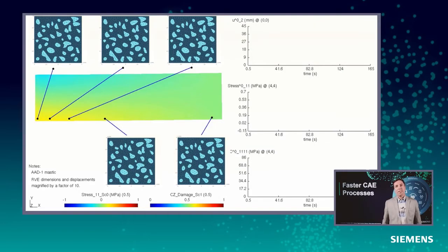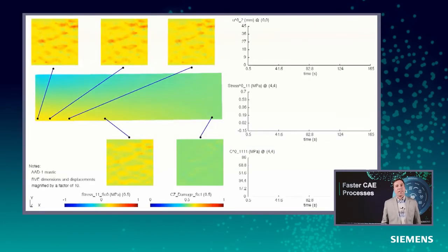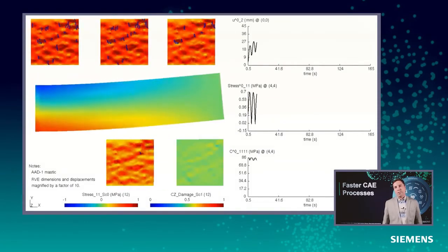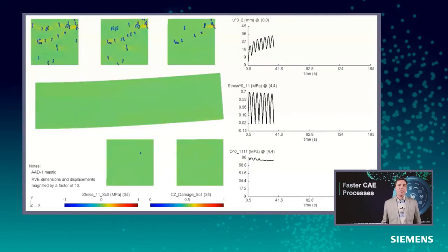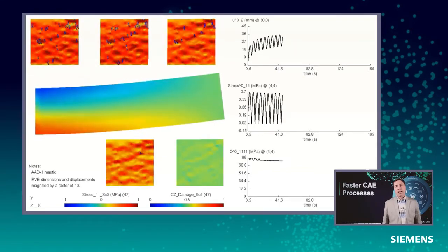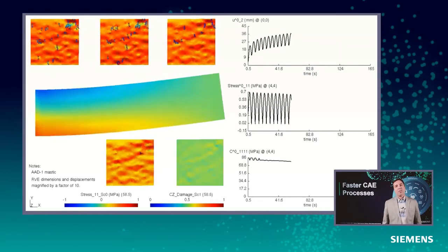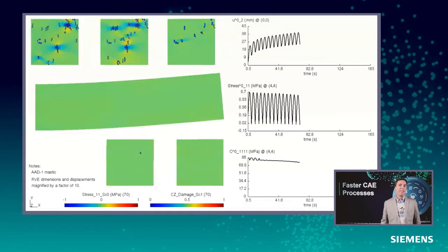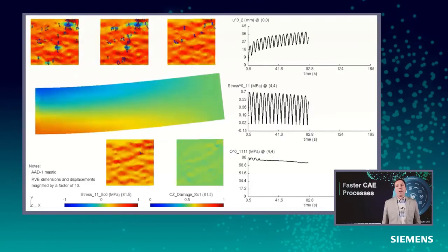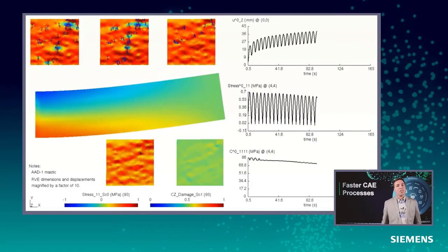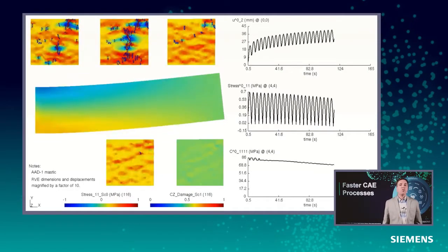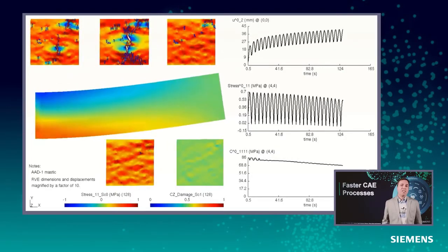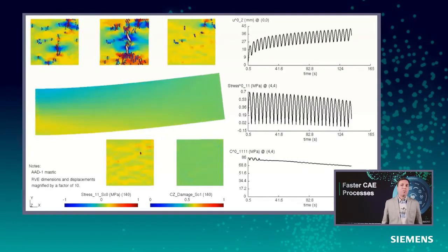In this latest release, we've made crack modeling capabilities faster, as cracking is a very important consideration for advanced materials. Micro and mesocracking in advanced materials are difficult to model with the finite element method, and in Simcenter 3D 2021.1, we've made the task easier by adding full representative volume element separation and automatic insertion of cohesive zones in between different materials. Microstructural models now allow for full mesh separation for a crack to propagate completely through a material.